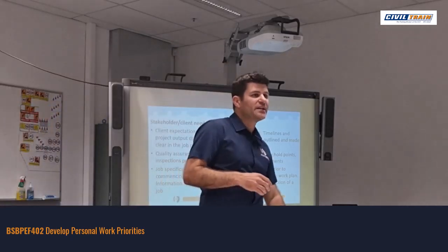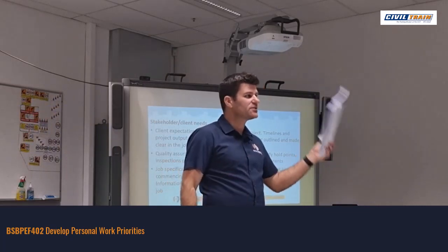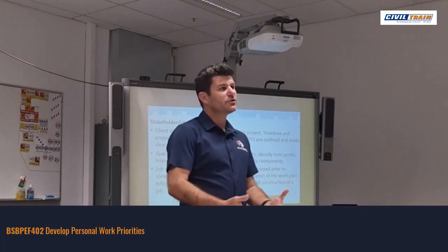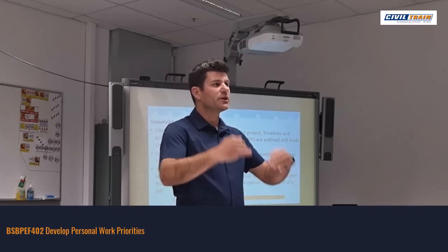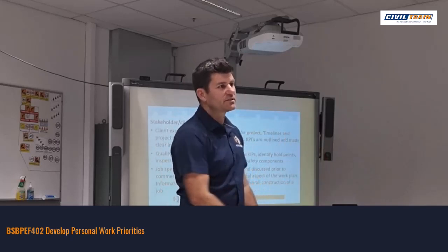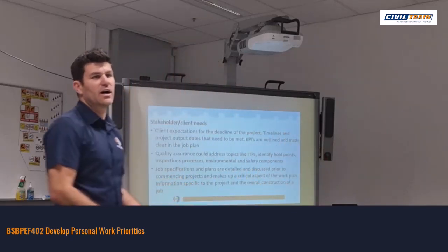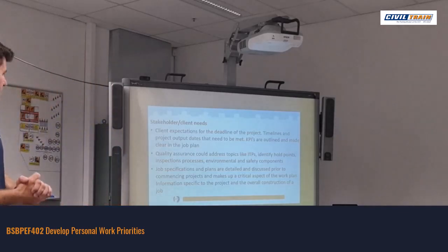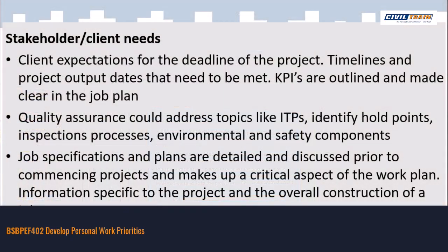One thing they always talk about here is compaction testing and soil compaction, where obviously if we do any works, we can't then start building on top of that until the results come in to say that we've achieved our pass marks to continue with construction.